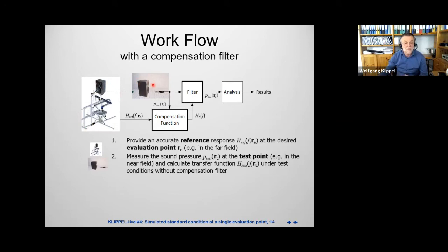Okay, and here is your microphone placed, maybe also at a strange position, too close or at a different angle. And then we have to do a measurement, and we are calculating then the correction function by using the reference data. The reference data are usually required at the evaluation point RE. So that means if you change your mind where the reference point is, you can do it with the holographic processing at the last minute.